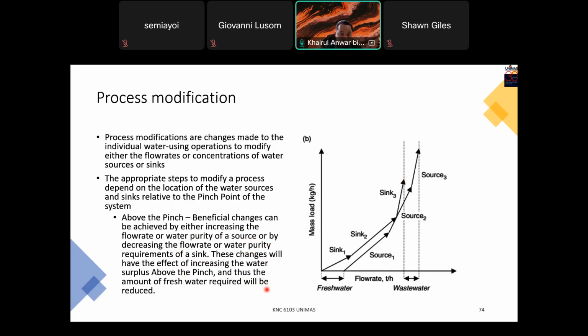The same thing for the paper. Go to the paper, page 3179. Regeneration above the pinch. Water sources in the region above the pinch are partially treated to upgrade their purity.